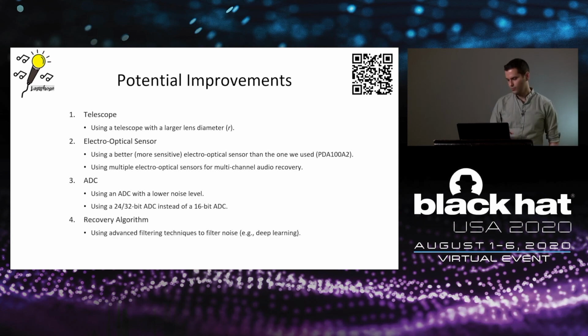And also, I mentioned it briefly, but we actually used only standard techniques of audio processing, which involves basically bandstop filtering and high-pass filtering and some equalizer and some standard denoising techniques. Today, there are much more advanced filtering techniques to filter noise from the signal.